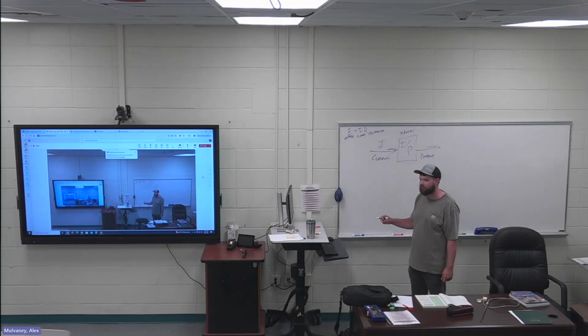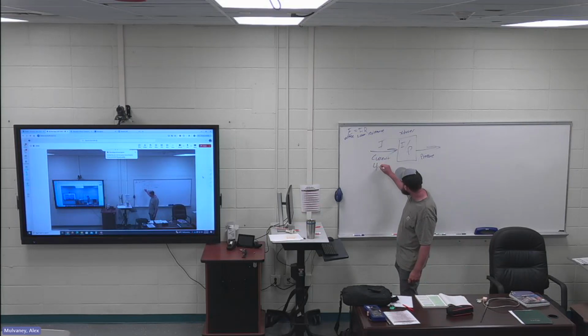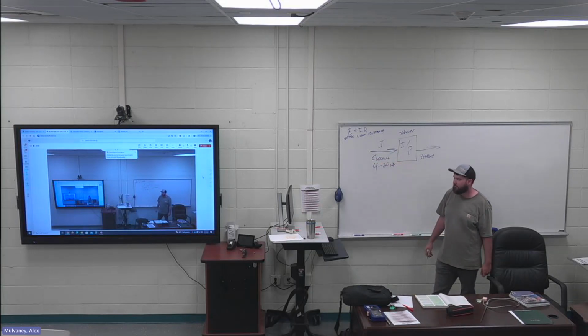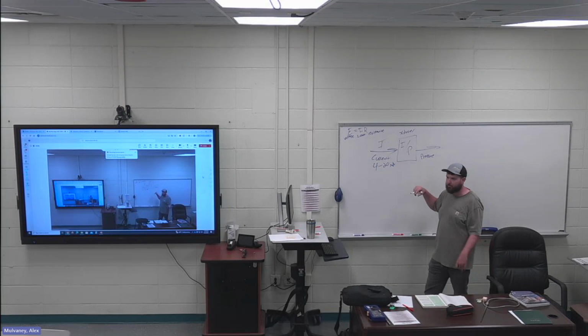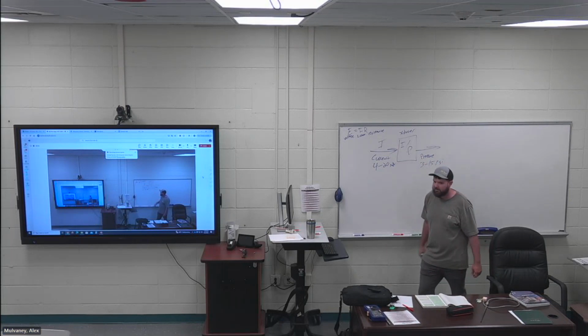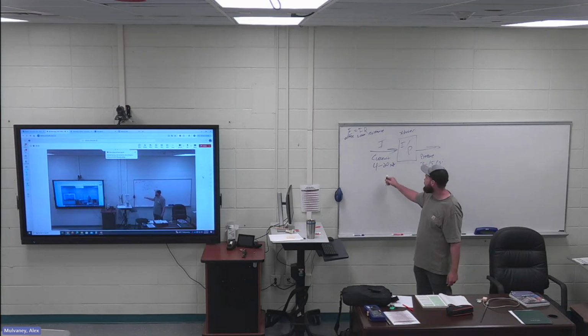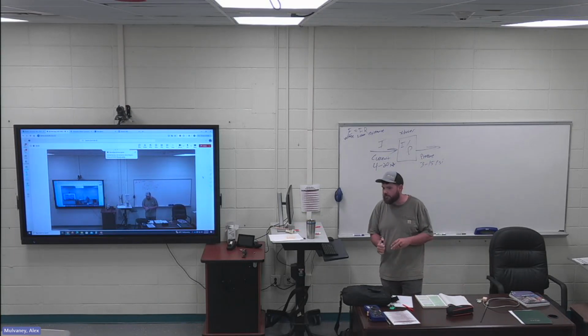Milliamps. What specific milliamps? 4 to 20 milliamps coming in. Then a regular output pressure would be like 3 to 15 psi. So that transduces, that changes current to a pressure. Most common type of transducer.